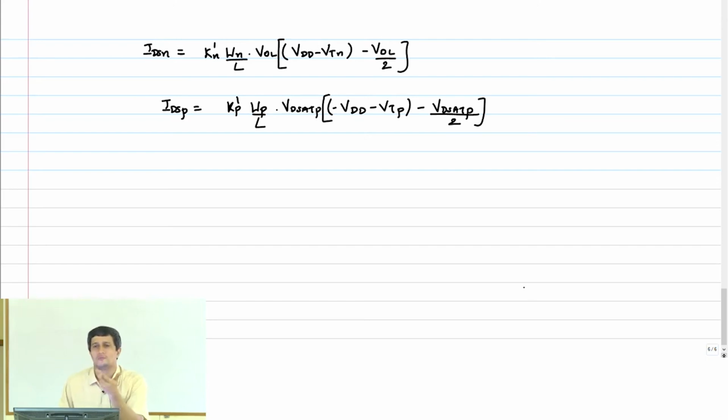Now, VOL is a very small number. So VDD minus VTN minus VOL by 2, I can approximate as VDD minus VTN.